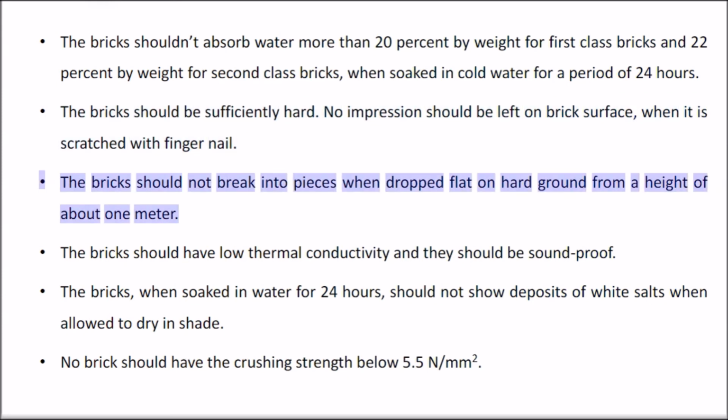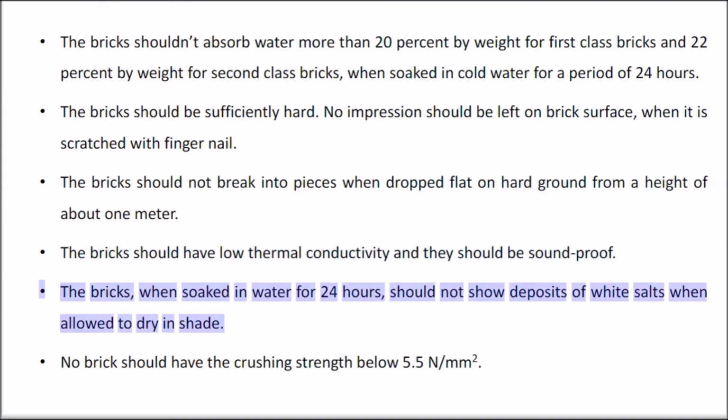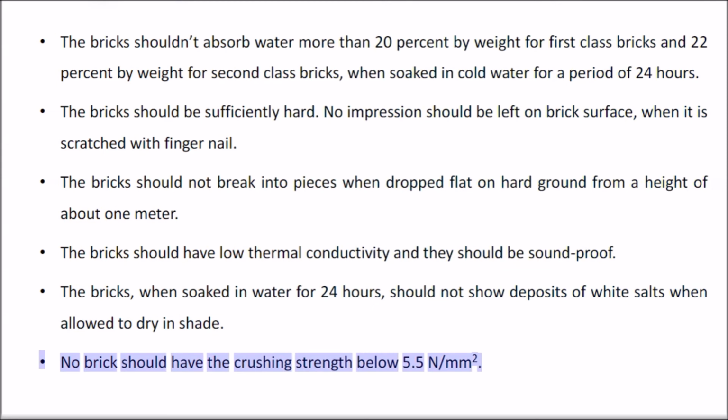The bricks should not break into pieces when dropped flat on hard ground from a height of about 1 meter. The bricks should have low thermal conductivity and they should be soundproof. The bricks, when soaked in water for 24 hours, should not show deposits of white salts when allowed to dry in shade. No brick should have the crushing strength below 5.5 N/mm2.